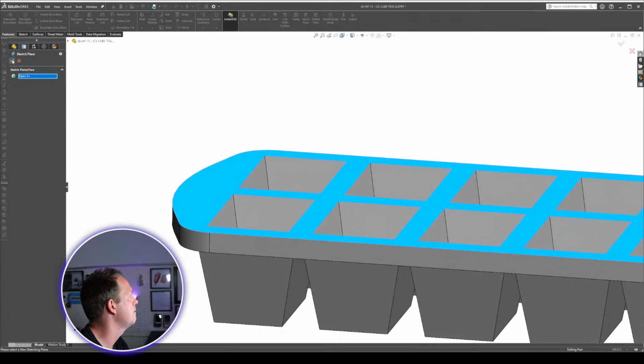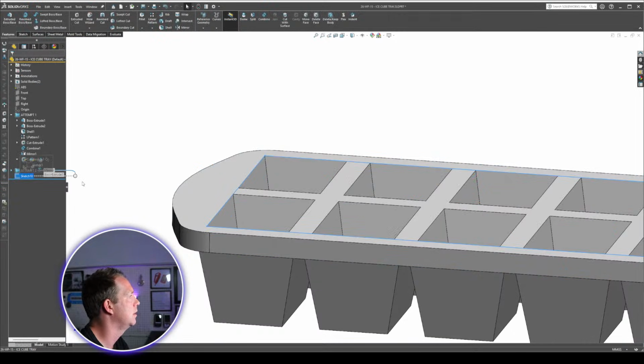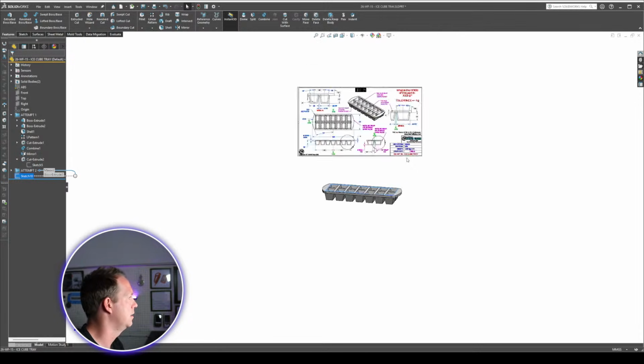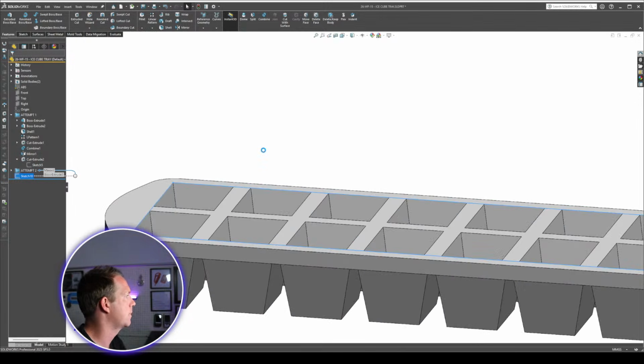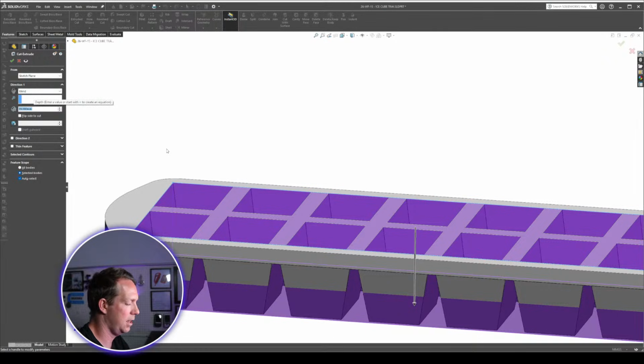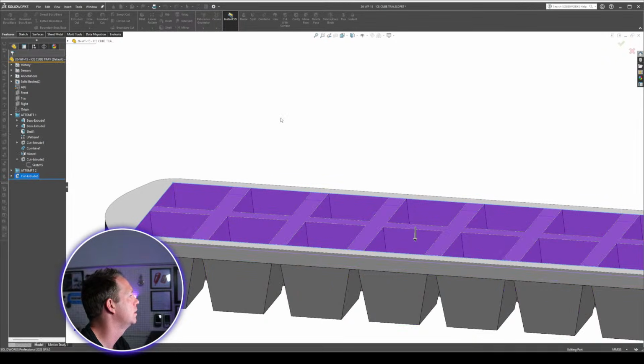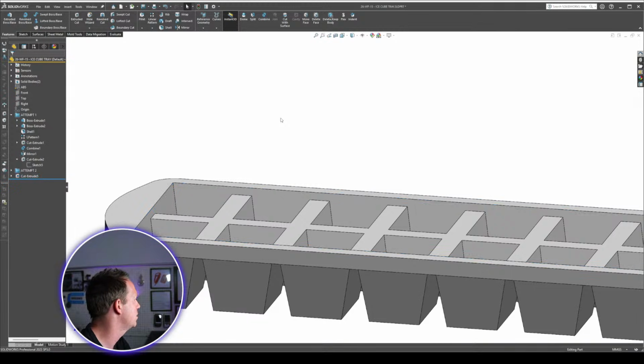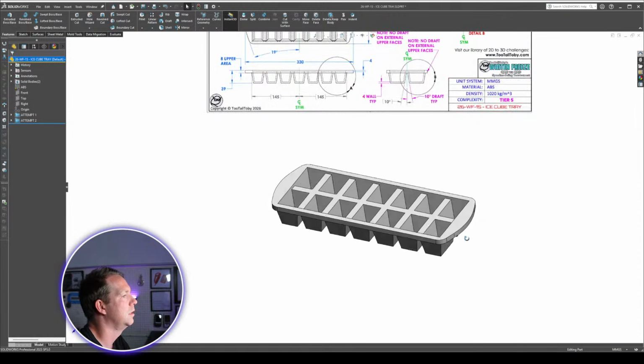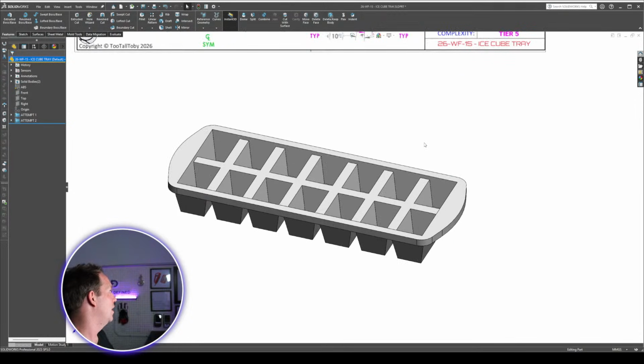So this edge is on here. All right, then I cut it down. Come down 4 millimeters, draft 10 degrees, and there we match. That is the very quick way to do that one. So only a slight efficiency gain. Yeah. Okay.